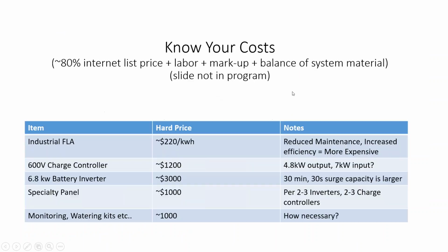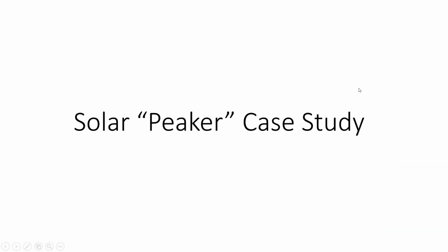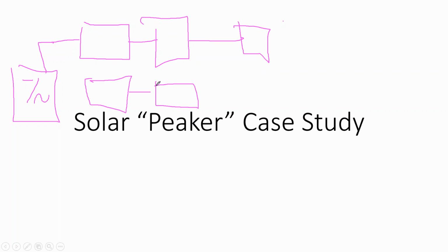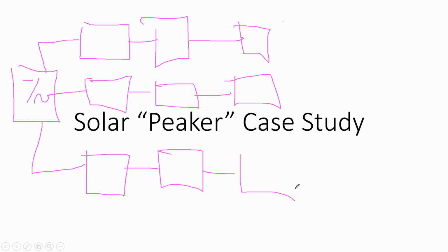But I guess the last thing that I want to say about batteries is another thing that I learned out of this: sometimes it can be a little bit hard to locate the batteries next to the inverter. Let's assume that this is our battery bank and here's our inverter on the wall. We ended up going with 2 circuits of batteries. And when you have your batteries, it's very important that you draw the same amount of amperage out of your batteries.